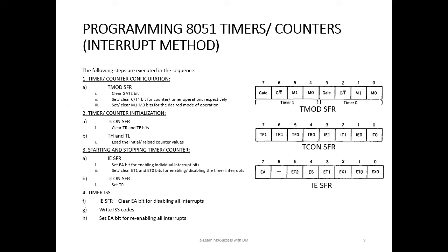We will broadly divide this method of programming delay into 4 steps. They are configuration, initialization, the starting and stopping of the timer counter modules, and the interrupt service subroutine. Let us examine in detail each of these steps.